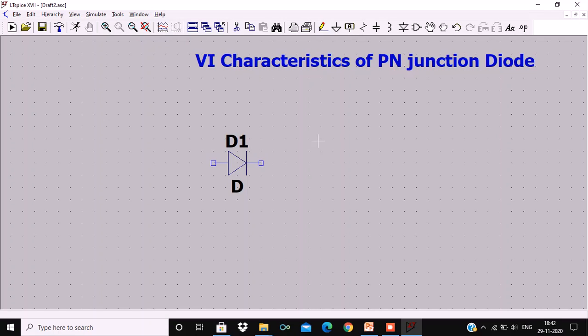First of all, the other component that I need is the resistance. So I am picking my resistance from the icons given. This is the resistor. I am bringing it on the board to a proper point. This is my resistance. I am placing it and pressing. My cursor has again become a resistor. In order to change it, I am pressing Escape.